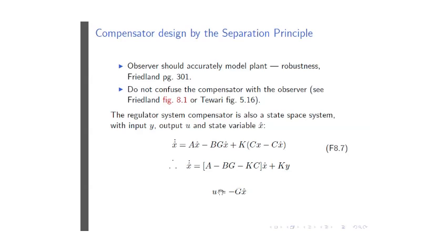It will measure the output Y of the plant, which is the input to the compensator in the computer. And you're going to do the number crunching in the computer, however you're going to do it. We'll discuss that next time. And your number crunching will spit out the output U in digital form initially, and then you'll put it through a digital to analog converter to get it as an analog signal that you're now going to drive the plant with.